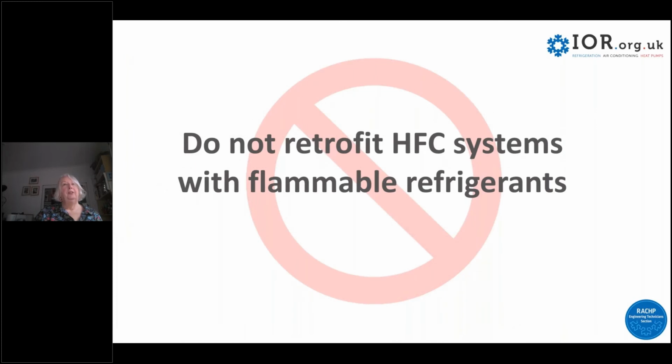And as I said earlier, specifically with R32 systems, but with all refrigerant systems, don't retrofit a non-flammable system with a flammable refrigerant.